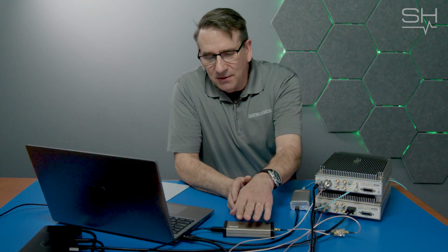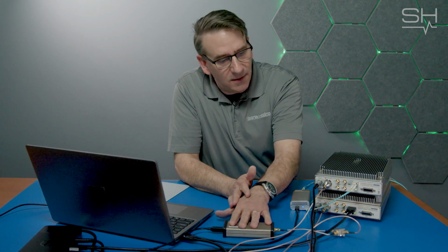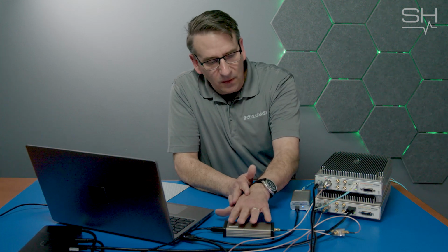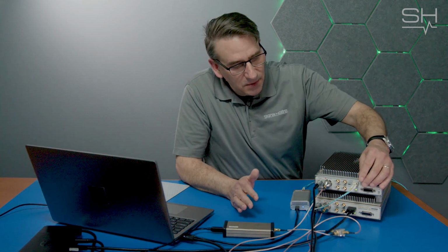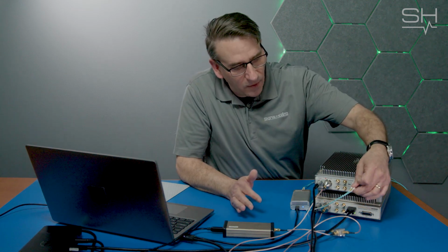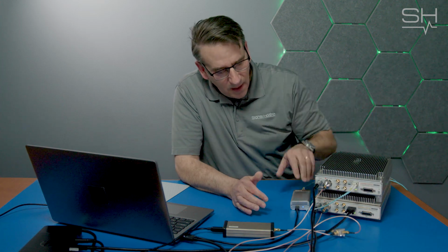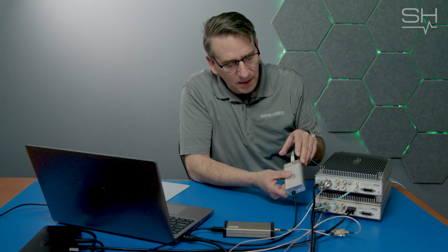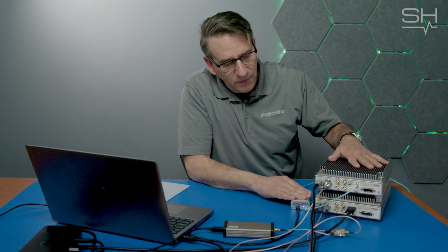I'll be generating signals using the VSG25. I chose the VSG25 because it can reliably give me about 100 megahertz of bandwidth out, and I need to be able to show one of the key differences with the two platforms. I've got an SM200C, and the major hardware difference is an SFP Plus port for interfacing to the PC. I'm also using a QNAP 10 gigabit Ethernet to Thunderbolt adapter to interface to the PC. So that's a big difference with the SM200C.